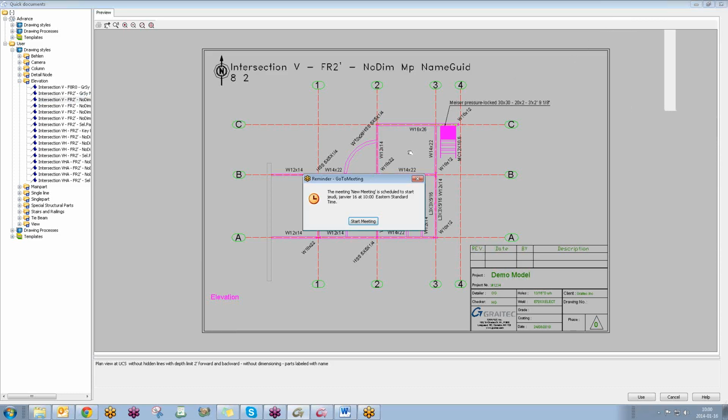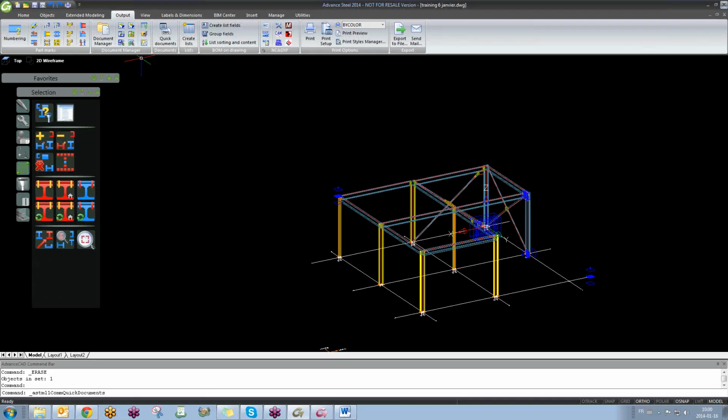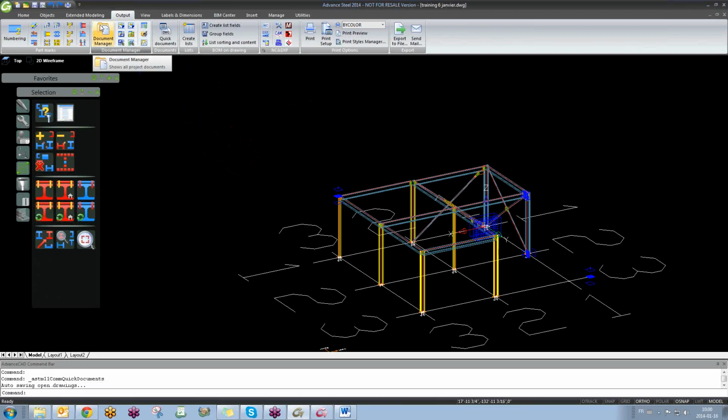Any other questions? So let me say, if I had that beam right there that you're showing on this drawing, framing to that wall, and let's say I had an end plate connection or a double clip angle connection, and I had bolts embedded into that, or expansion bolts, wedge anchors or whatever, framing to that wall for that connection. Are you talking about the connection on the wall? Yeah. Would it show up on that framing plane you just showed there?